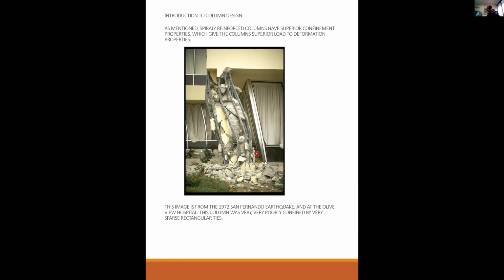The building, you can see the drift of the mullions here. The building suffered from what's known as a soft story. That's another big no-no in seismic design. But the soft story allowed the first story to drift. The rest of the building stayed more or less upright, and the whole first story drifted over something like 1.5 feet, maybe 2 feet.